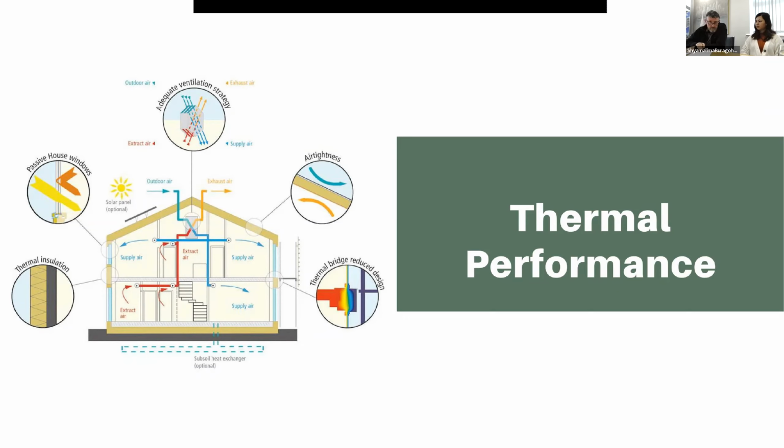So turning the same building by 90 degrees could improve its performance. The geometry of the building, such as long, narrow buildings with the long edge facing in the wrong direction, could impact the thermal performance of the building. So to change the proportion would simply improve it without increasing or decreasing the floor area.